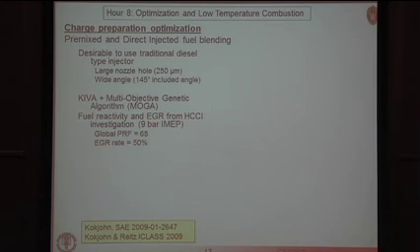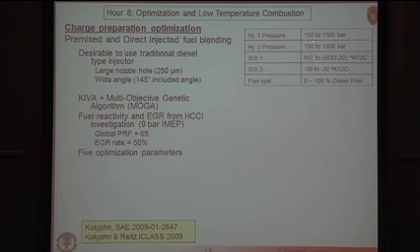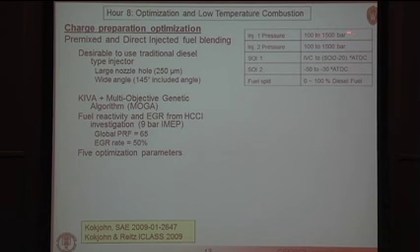We're going to choose PRF 65 because that gave us good results from the HCCI simulations, and an EGR rate of 50%. And the idea here was we were going to allow 2 diesel injections, an early injection, and we're going to even allow the injection pressures to vary over a wide range from 100 to 1500 bar and be different for the 2 injections.